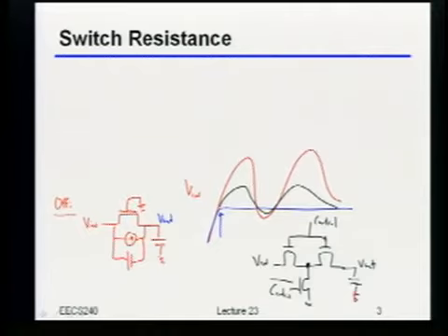Okay? Now, this isn't free, unfortunately, because I said earlier, I have to split that switch in half. Right? That means that for sort of the same width, I'm going to have twice as much resistance. Just ballpark, roughly speaking, if not even maybe a little bit more than that. Okay? So, it doesn't come for free, but if you really care about isolation, actually it's a pretty good idea to do this. Any questions?